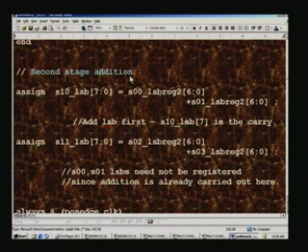In the second stage, we have from the first stage four results coming, S0 0 through S0 3, and we are going to add them here. Once again we adopt the very same strategy that we had done earlier. We take the whole number and bifurcate it into roughly equal parts, call them LSB and MSB, and then add only the LSB first. That is what we are doing here. This LSB is added at the first stage as S0 0, and to S0 1, that was also the first stage output, second output. So is the case for S0 2 and S0 3, which are the other two outputs